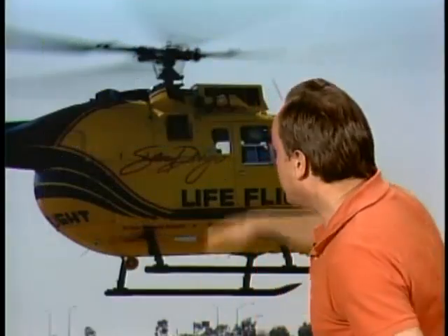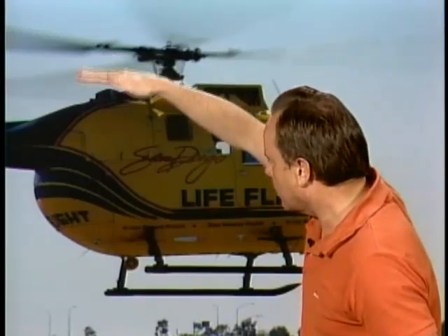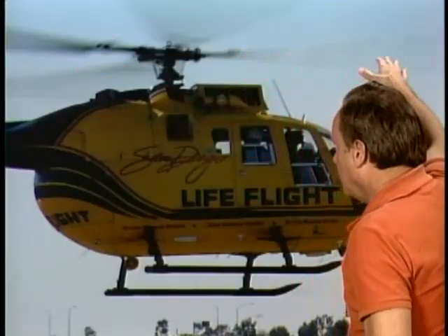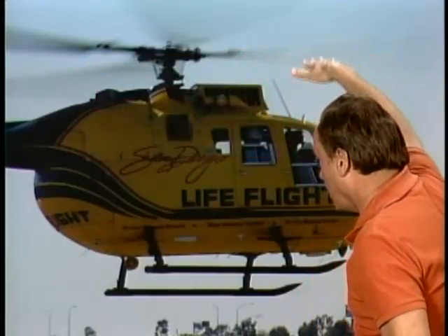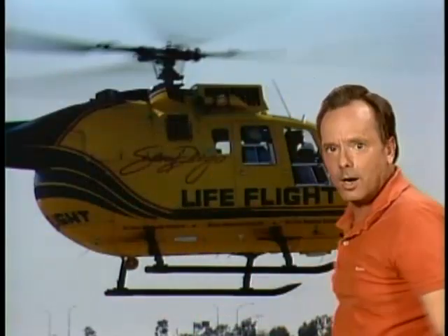Now, let's assume you're flying along. They want you to know, of course, there is a downwash effect as the helicopter is flying along, and there is a greater downwash effect through the aft part of the main rotor disc. The reason for that is, of course, as the helicopter starts this front air going down and flies through that downwash, it gets greater at the aft part because the helicopter is moving into that air. And what is that effect called? They ask you on the test, and the answer is that effect is called transverse flow effect.